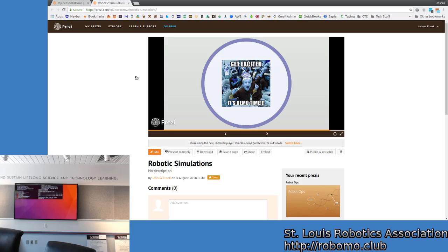ROS doesn't have a discovery service? No, actually, ROS 2 is supposed to be adding a discovery service. Although I haven't used ROS 2, so it's hard for me to talk too much about it. But I've read about what they're trying to do, and this is one of the things they're trying to fix. Now they have either a messaging queue, or they're using a DDS network system to do discovery. But I think you still have the same issue of having to get the IP address of a master or a peer in that network. I guess it's going to be a little easier because now it can just be a peer. If you connect to anybody, you've connected to everybody.